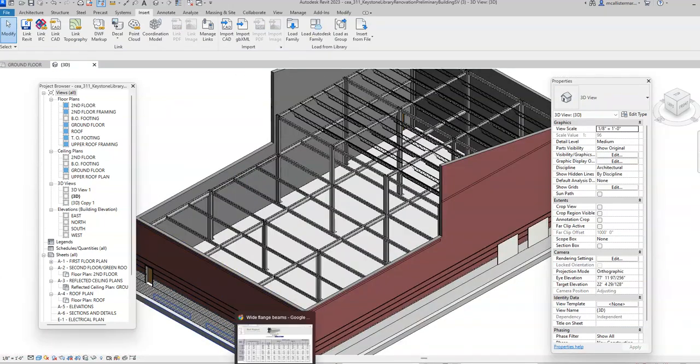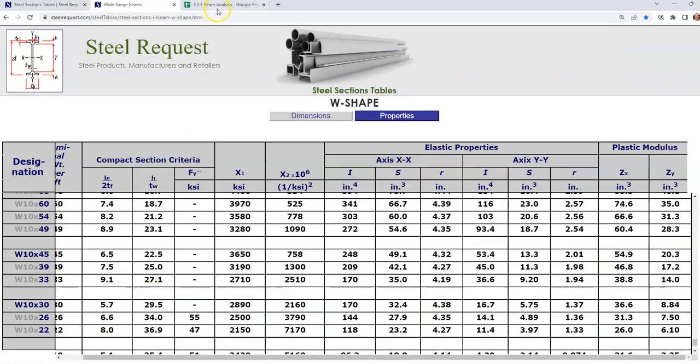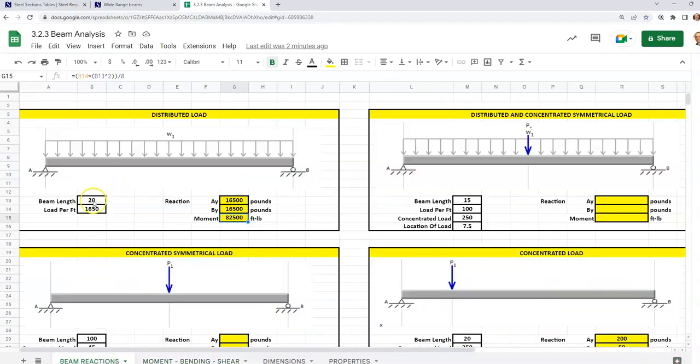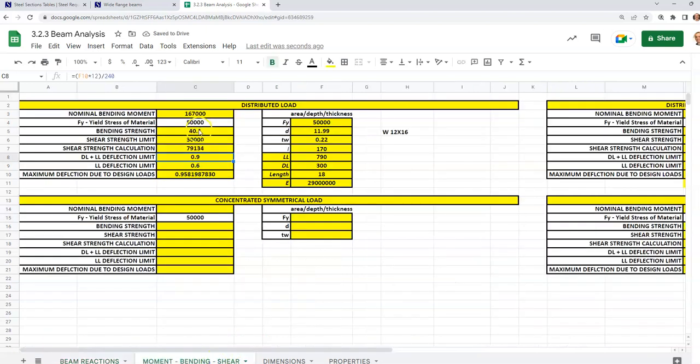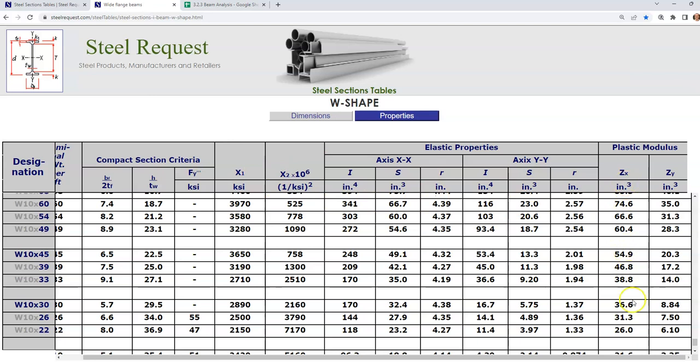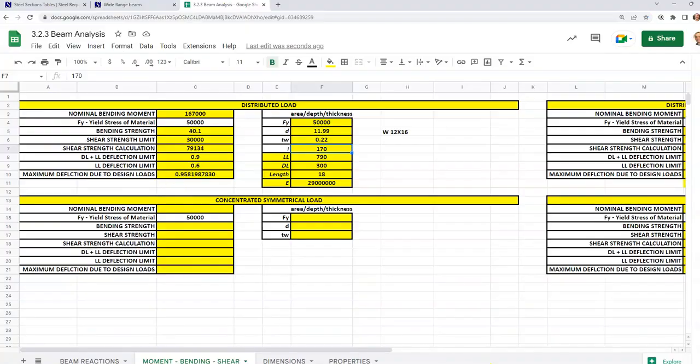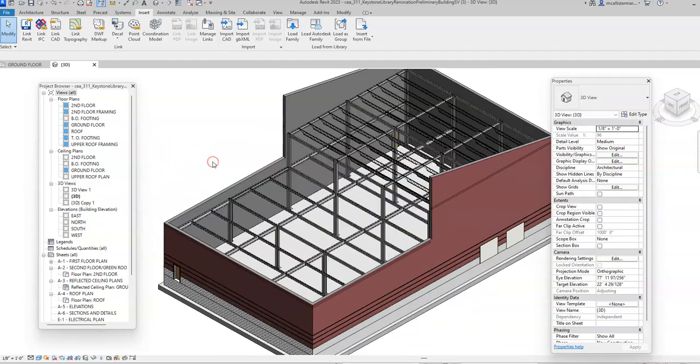Now I would need to change the size of my beam should I say that I miscalculated the amount of weight acting here. So if I said actually it's going to be 2,000, that's obviously going to change this number to a different number, and we would have to go back and try to find this inertia number to get that below 0.9. Again, that would take us back to our spreadsheet and along over here, to find what beam can we find that meets this requirement that keeps it below the deflection here. So this is how we go about sizing those beams.